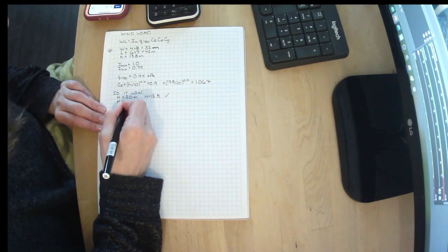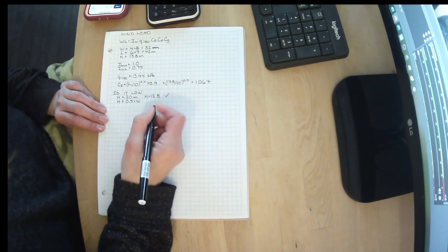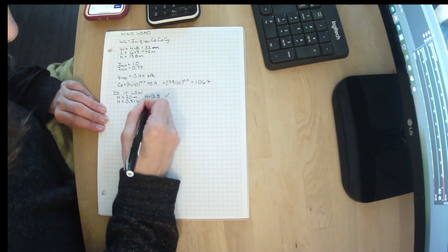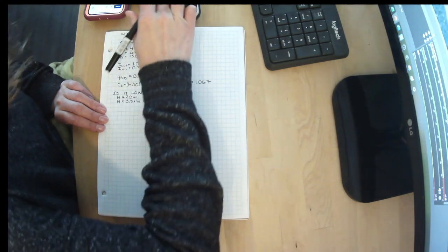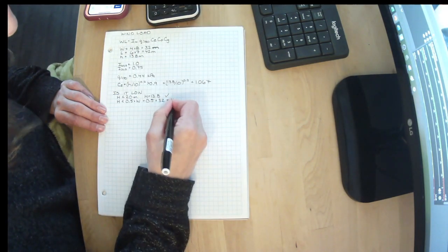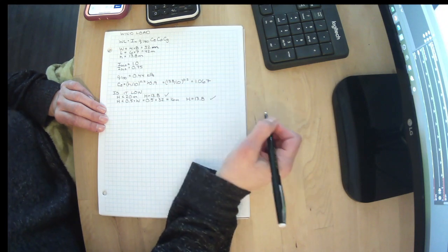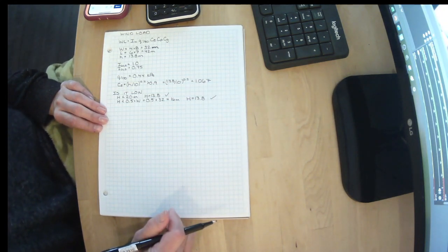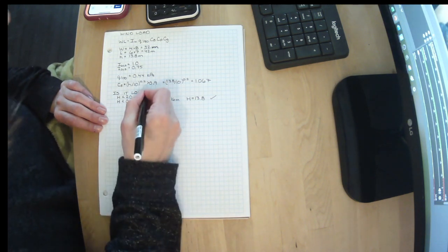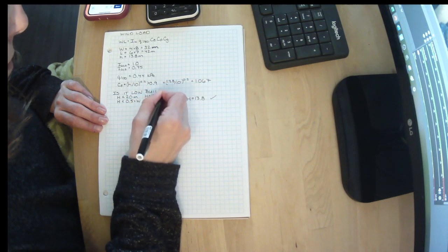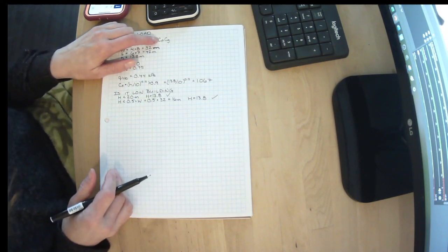H needs to be less than 0.5 times W, or the smallest dimension of the building. So we have 0.5 times 32, which equals 16 meters. H equals 13.8. So we do have both of these. We get to use the low category. Not low importance, it's a low building. It's not a high rise. So that means the only thing left to figure out is our CP and our CG.